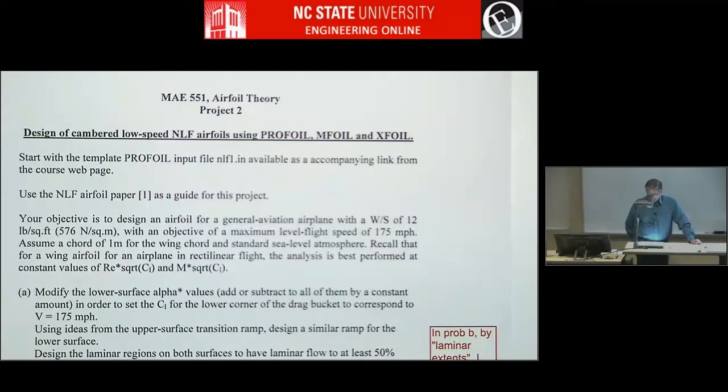So project 2 is a little different from project 1. Project 1 was a project where you have one figure of merit and the objective is to increase that figure of merit as much as possible. Project 2 is not like that. It's more of a parametric study, a design study where you design a good baseline airfoil and then change thickness and change something else and change pitching moment and see what happens. What are the trends in cambered airfoils as you change one thing or the other?